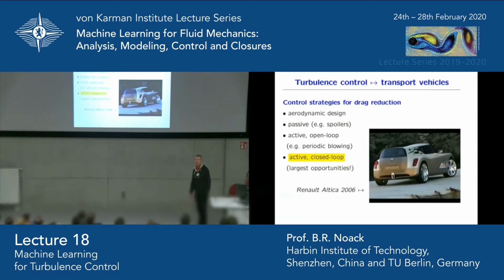Where can you see that? What is aerodynamic about the car? Yes, good. What else? Oh, look at the wheels. It has very small gaps. So this is one thing. Look at the bottom. It has a diffuser, so the wake is reduced. And now the question is, what could we do more on this car to reduce the drag even further?